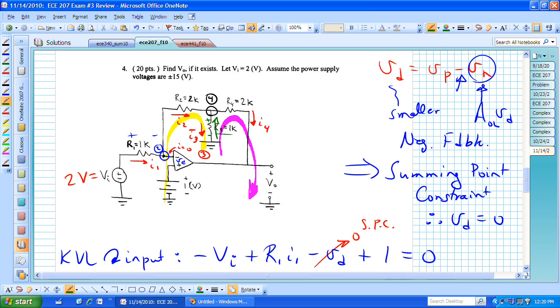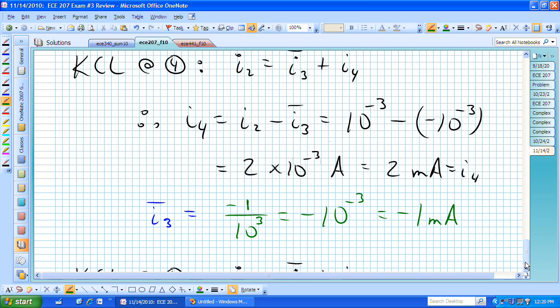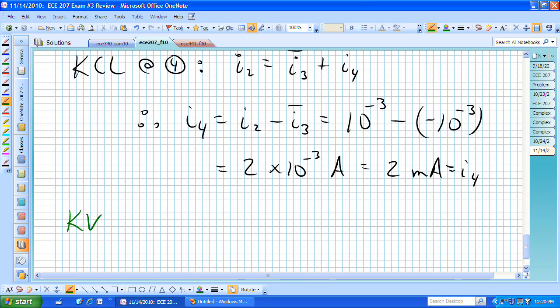Meaning the voltage dropped across that resistor is from top to bottom with the passive sign convention for I sub 3 bar. We'll then go this direction, which is consistent with I sub 4 that we've labeled, and consequently that voltage drop will be from left to right, and then we'll come down through V0. Let's now do that for KVL at the output.